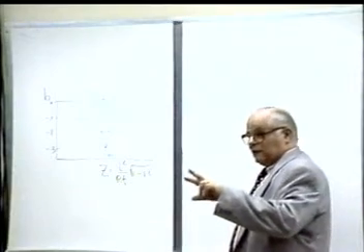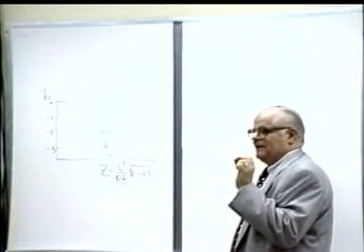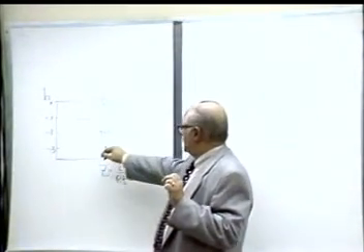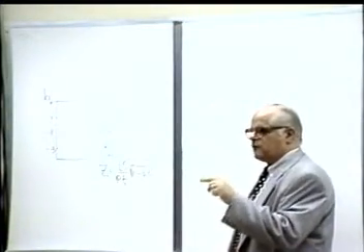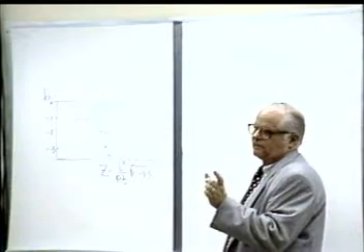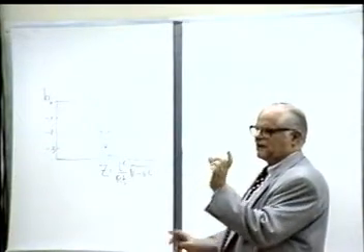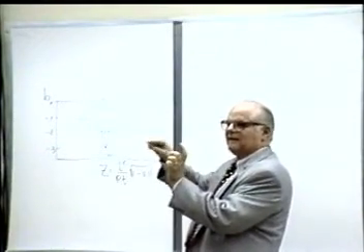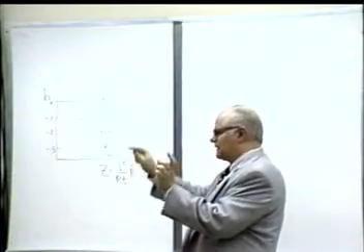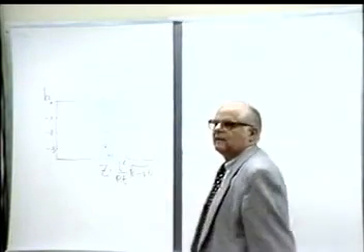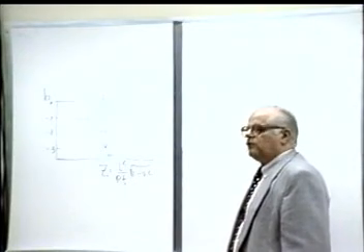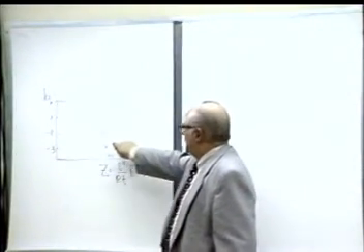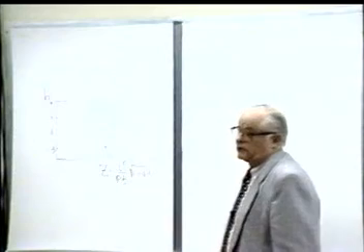Now, what one has to caution there is that this increased imperfection sensitivity occurs for imperfections in the form of the buckling modes. Right? So imperfection 1 has to be precisely symmetric, imperfection number 2 precisely anti-symmetric. Okay? But certainly that will be one of the conclusions that has to be drawn from this investigation if in the end such a result comes out.